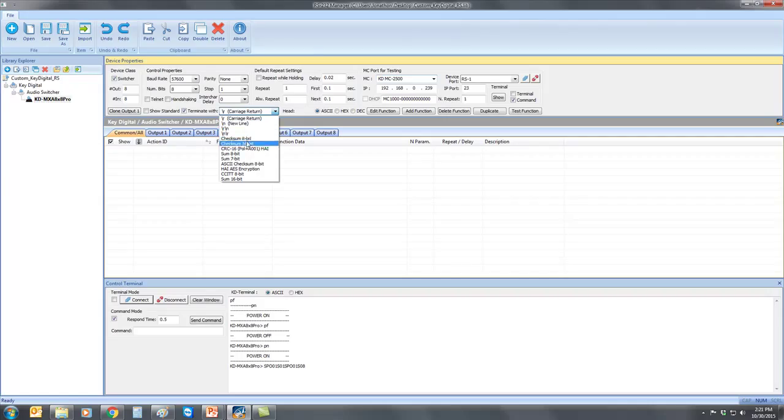And in other cases, devices that are hex controlled, of course, we support, as we see here, ASCII, hex, and decimal formats. Some devices need checksums, which means they have different hex bytes, and you have to add them and come up with a total as one of the bytes. So we support that, and we can automatically add that in for you, whether it be 8-bit or 16-bit, and all sorts of other terminators and automatic inserts that we support for your various devices.